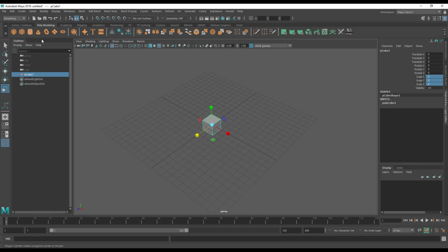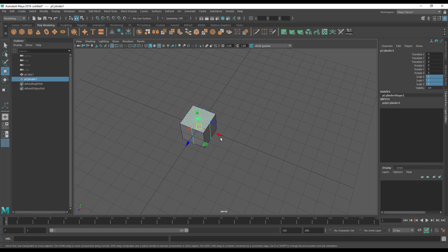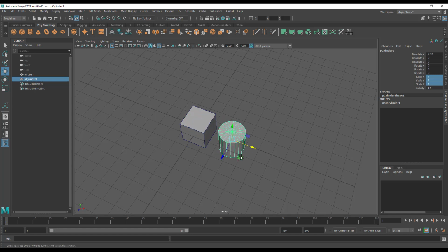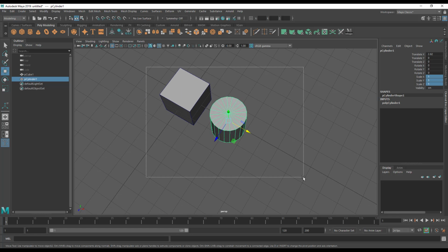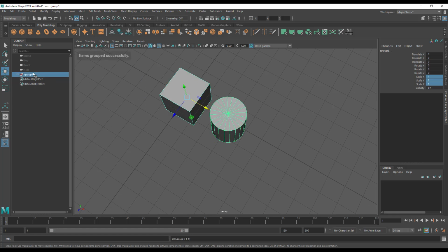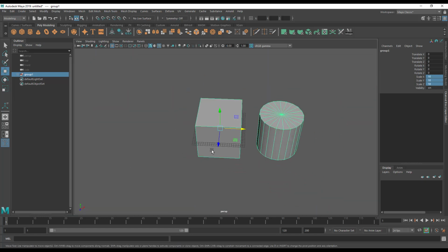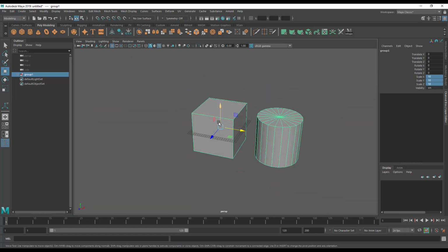So what I would recommend is for you to get all the things that you need. So let's say like this guy here. And group them together, so Control G, and then just make the entire group node an order of magnitude bigger. So 10 here. And that will scale everything correctly for when you want to print it.